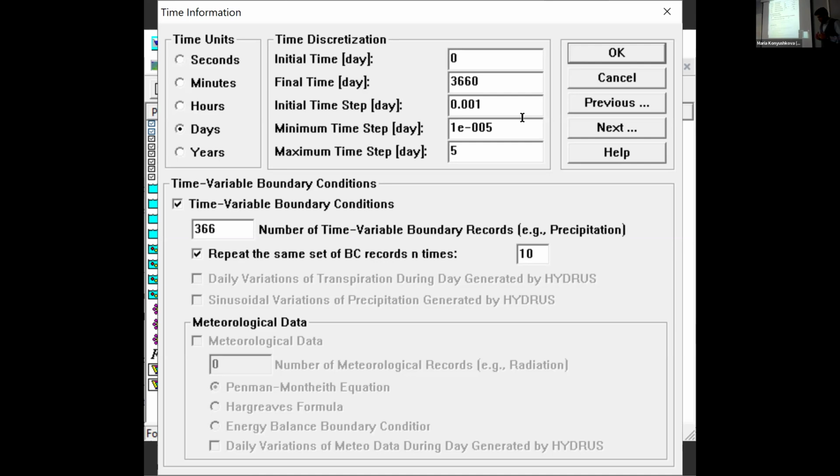Yes, it's calculated based on the composition of the solute that we give to the model as an initial condition. Based on that, it starts with this EC, because we don't give the EC to the model. We just give the composition of the solute. Based on that, it starts to calculate the EC, the EC of the soil, and it's not the EC of the paste extract.